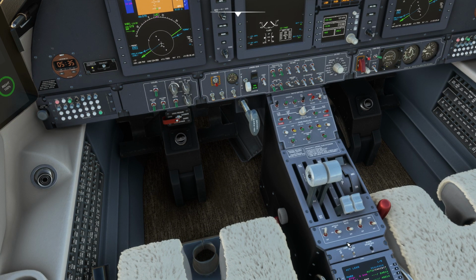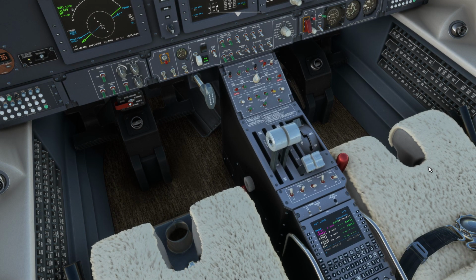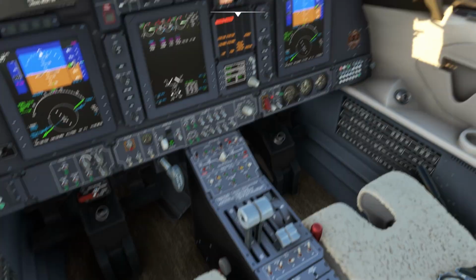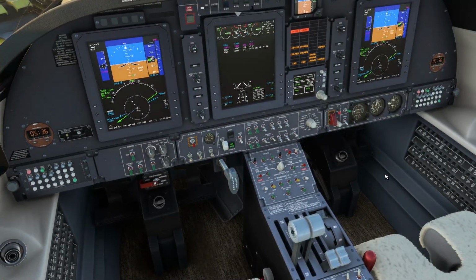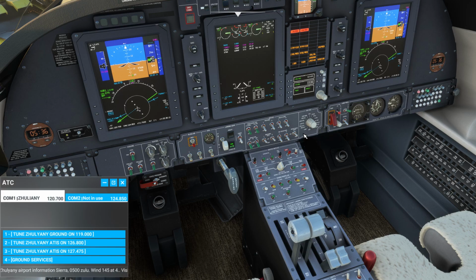Right, we want anti-collision to ground. Anti-collision to ground switches on your beacon. If you go to air, you get your strobes on. Wing lights, we want the flight crew to know that we are about to start engines. Many airlines do have it in their protocols to get the wing light on. Transponder, for the transponder we actually need the clearance, don't we?